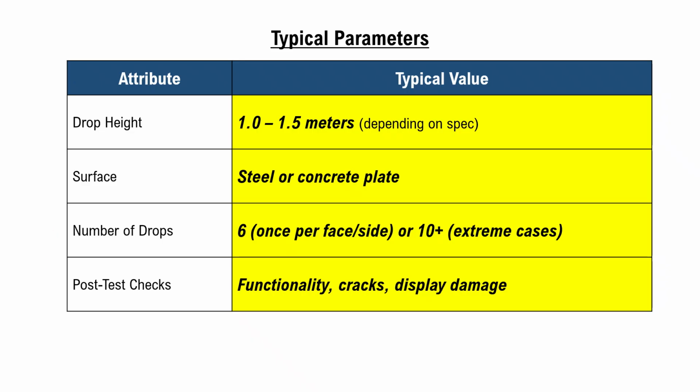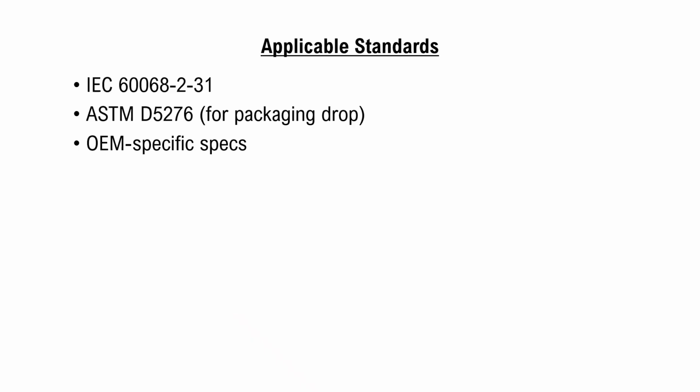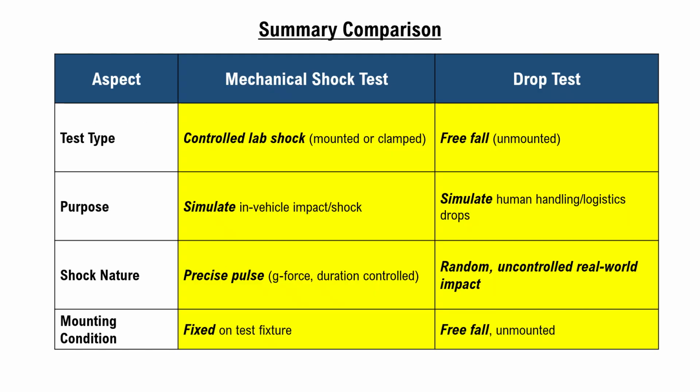Post-test checks: functionality, cracks, and display damage, etc. The applicable standards are IEC 60068-2-31, ASTM D5276, and finally OEM specifications.